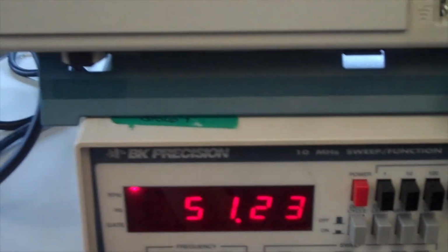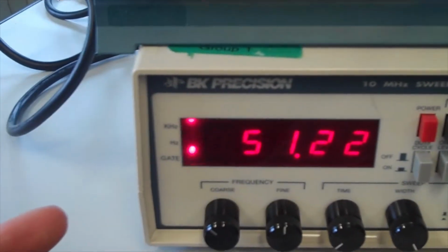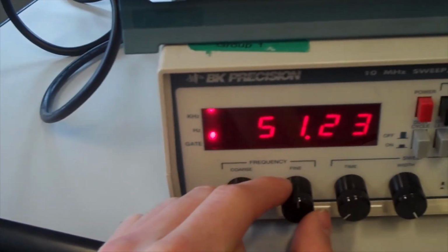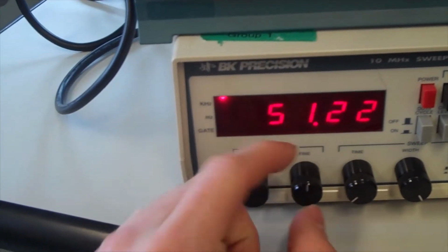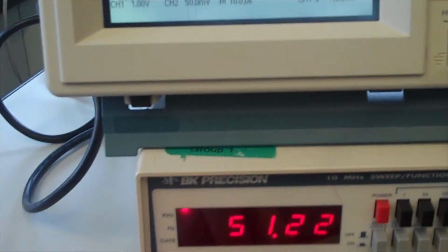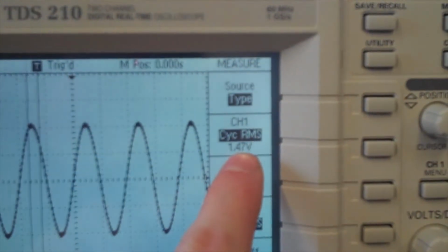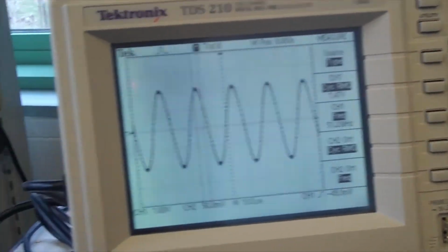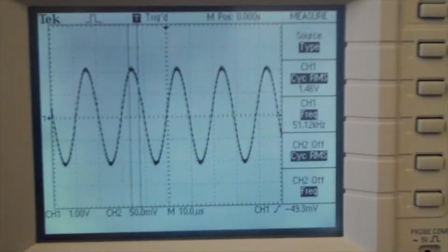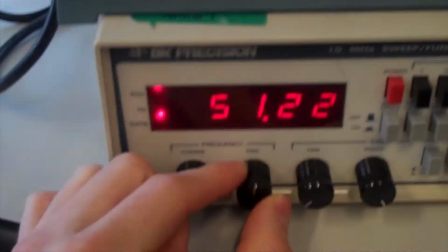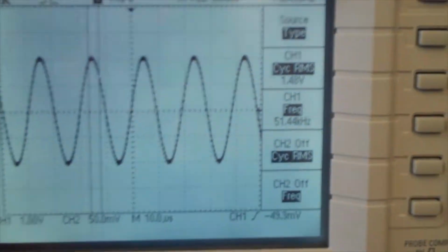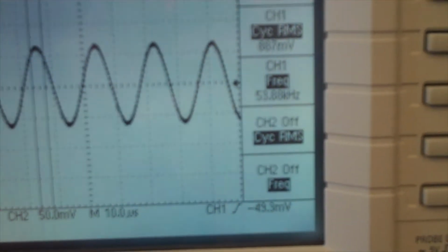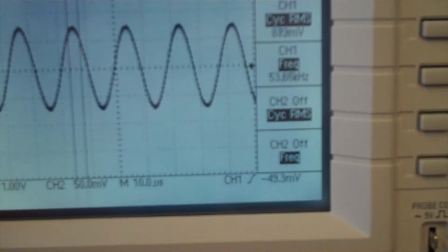Alright, now you're going to want to find your omega 1 and omega 2. This is done by finding half the RMS, and then turning this to the right first, and next turning it to the left, going to whatever the value of 1/2 that is. And I believe, what was the value? It was 0.7 something. Yeah, 0.7, let's say 0.74. So right now I'm going to turn this all the way right until this RMS value goes to 0.74. Oh, it looks like it won't go down that low. We're going to do the coarse one first.